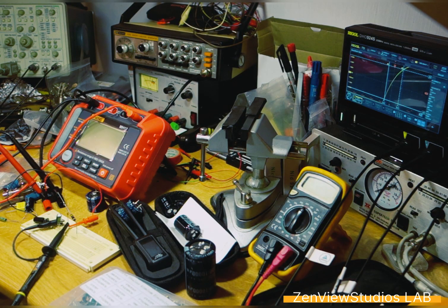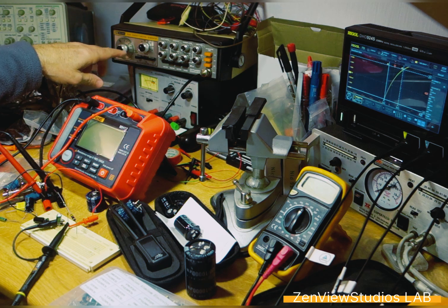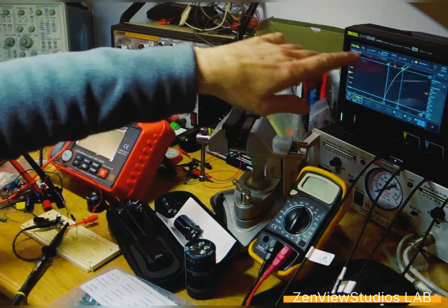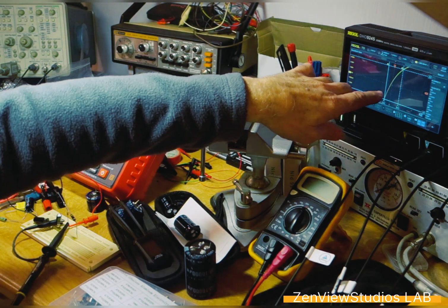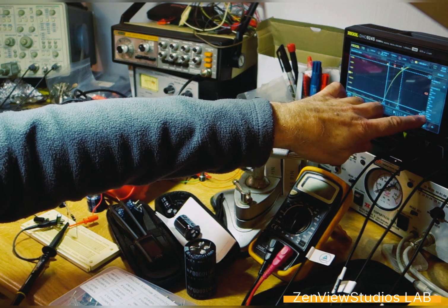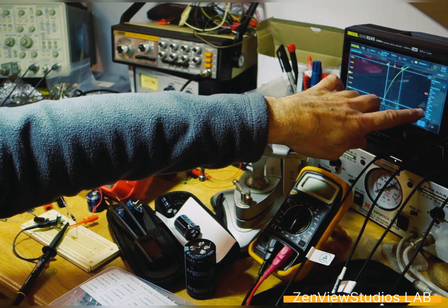One more thing. Another thing you can measure is capacitance, obviously, with a scope and a generator. Here I'm generating a pulse at about 10 Hertz, and with the curve I can measure the 63.2%. It's here 6.328 volts.